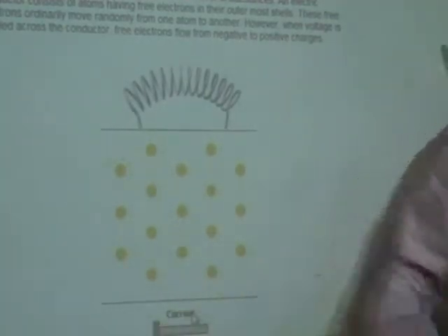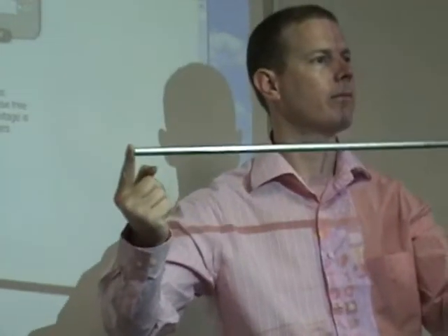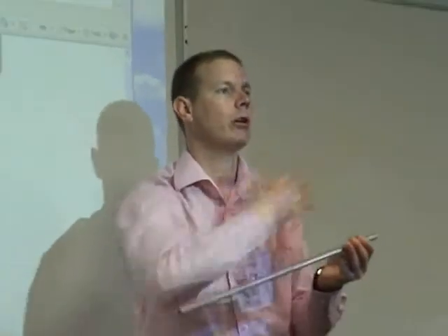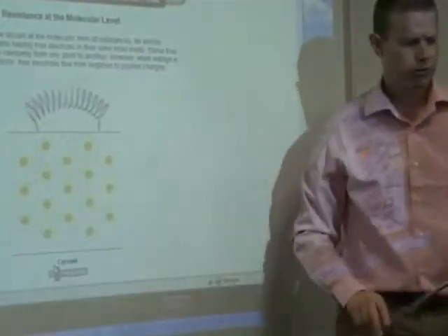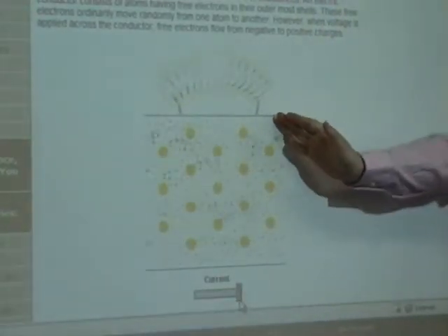What's misleading about this is it suggests that if I attach a battery, the battery supplies electrons to the wire. So it's like if I attach the battery to the two ends here, the battery would supply electrons. Why is that incorrect? Because the electrons are already there. All the battery is doing is making the electrons move around at a quicker rate, or making them move around where they wouldn't before. Even if you increase the potential difference, you're making them move around more quickly. So it's misleading because it suggests introducing electrons. If I make the current go bigger, it's suggesting that it's introducing more electrons, where all that's actually happening is it's making more and more of the electrons that are already there pass a point in a fixed amount of time.